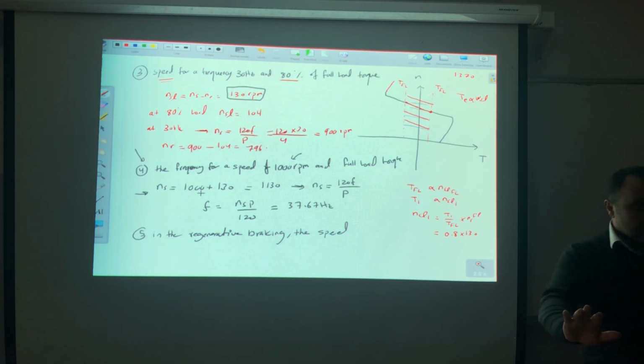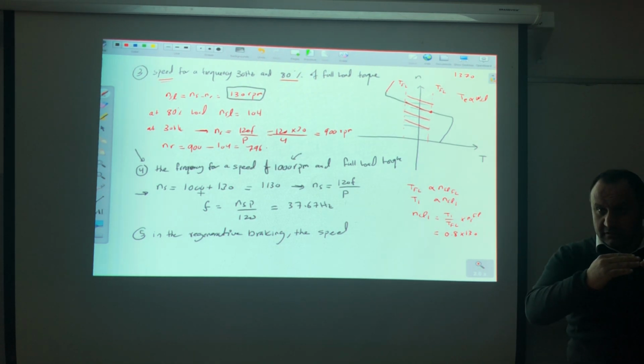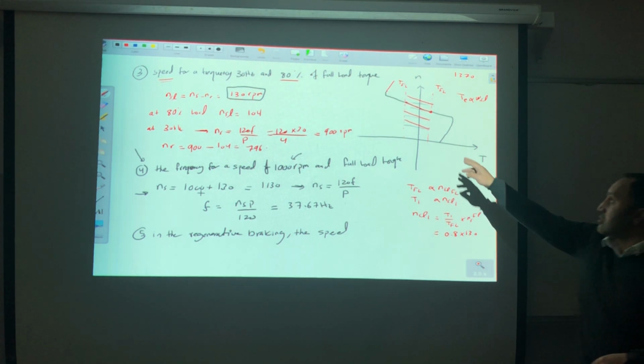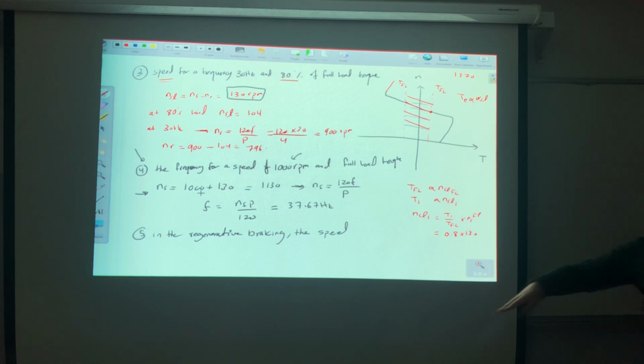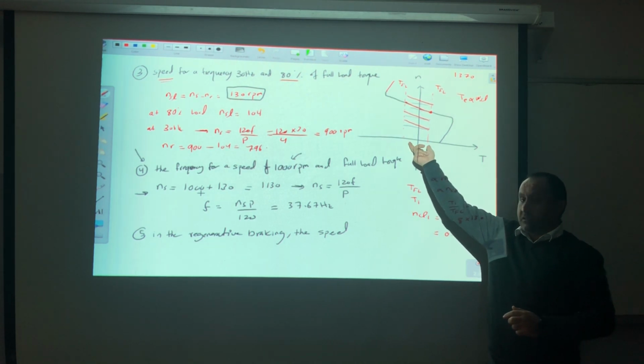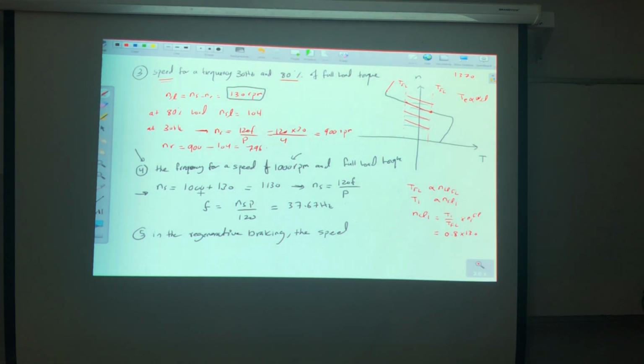I'm using V over F. Yeah? Which means that I'm now controlling the frequency and what? The voltage. Good? So simply, if I'm changing the frequency, those lines will change. Correct? While the lines are almost parallel. By the way, this is an approximation. Why? It's a valid approximation because I'm only discussing what? The linear region. And not only all the linear region, the restricted linear region between the full load on the motor side and the regenerative braking side. Correct? So those are actually almost parallel lines.